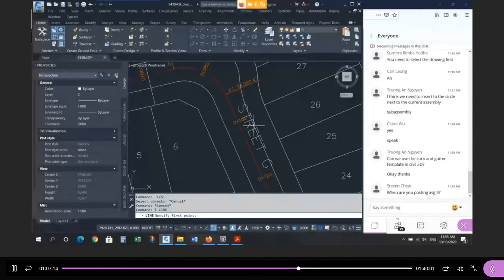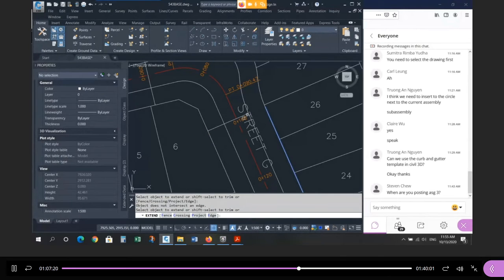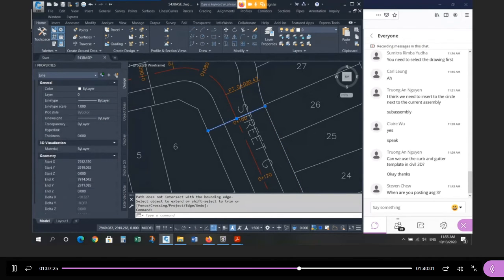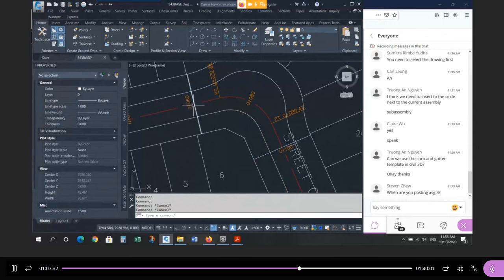And then where do you get your standard 20 back? Well, from the end of this curve, perpendicular and across to here. And that's where your standard 20 meter starts again. So between here and here is where you have your kind of abnormal width. And this is the point, the station value at the beginning and the station value at the end of the zone. So that's where you put your point. That's one station I need. This is another station I need. And then I project them.